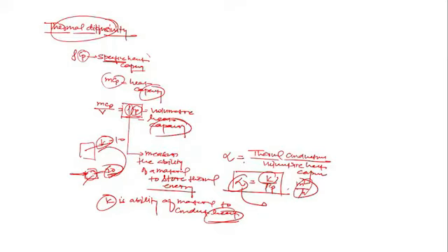So the ability of a material to conduct heat cannot be decided only by the thermal conductivity, because a material has one more property, called storing capacity. It can also store more. Clear? For example, here K is 10 and here K is 20, and here rho Cp is given as, let's say, 5, and here rho Cp is 15.